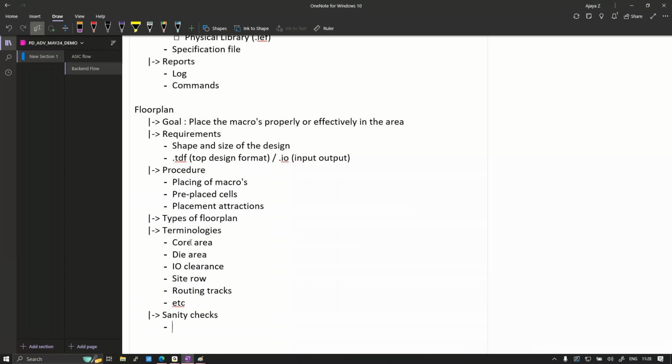During the macro placement, again, as I'm doing it manually, the macro placement is done manually only. If you have 400 macros also, you're going to do it manually in some industries. Each and every bit of information has to be analyzed. In some industries it has been automated, but the preference is manual placement.